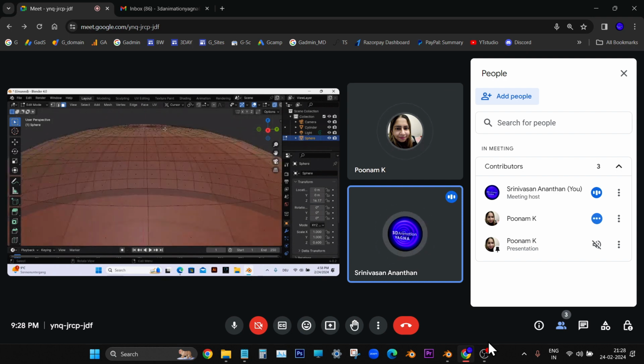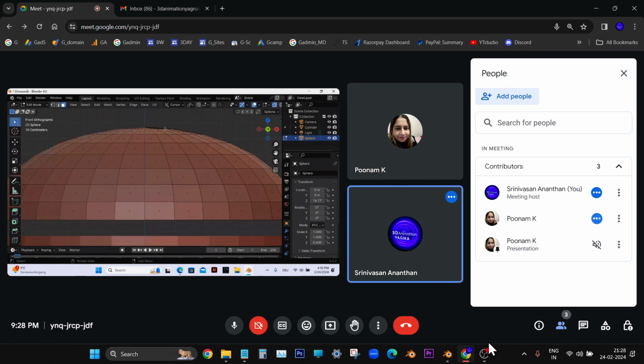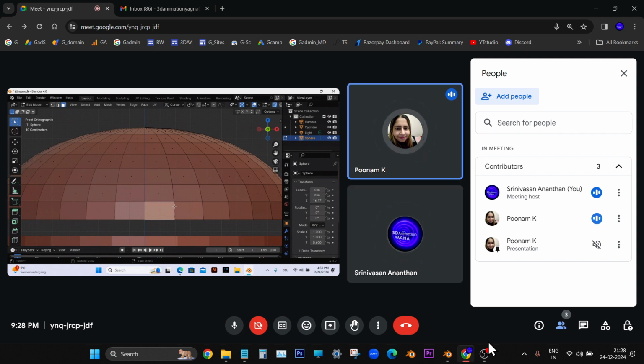Let it be in the same view, front view only. Bring your cursor to the same face. There is down, down, middle face. That face only. On that face, one edge is there, its four sides are there. Just now we selected the right one. Now just take your cursor to the top edge inside that face only. Now you press Alt and click on it.